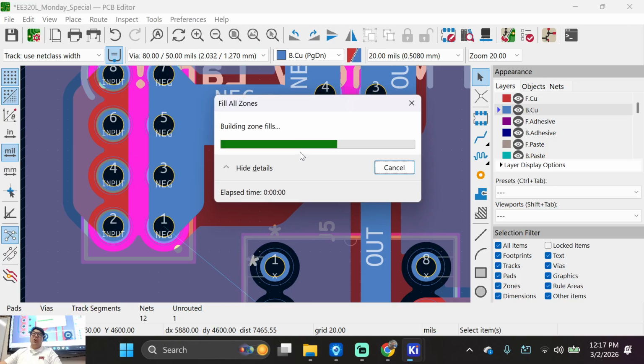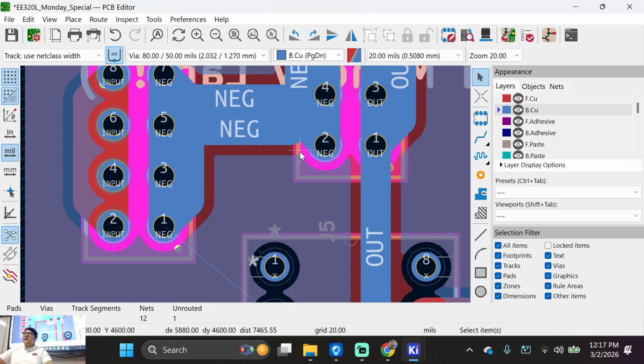So there's this thing called ground loops, which is basically when you put ground here and circle ground, and you can create an antenna. You can create PCBs that act like noise generators, and you'll wonder why your thing doesn't work. Like breadboards, for example: if you put a ground around your breadboard, you unironically create an antenna.